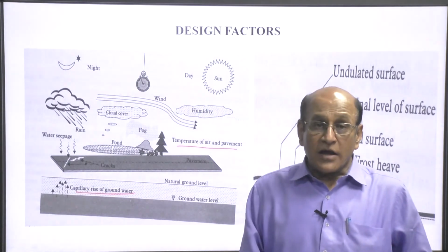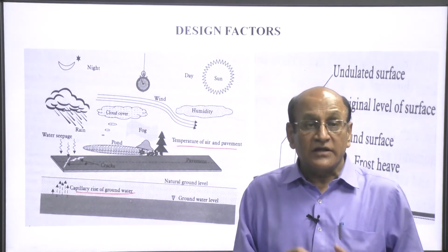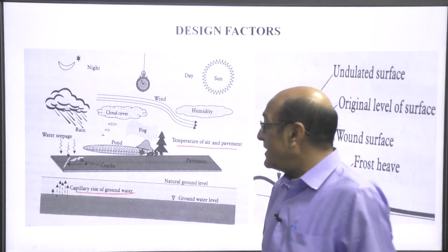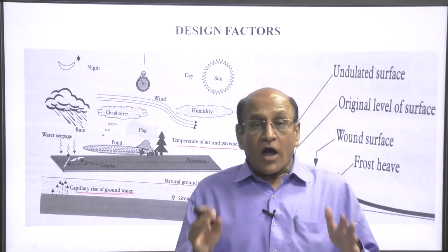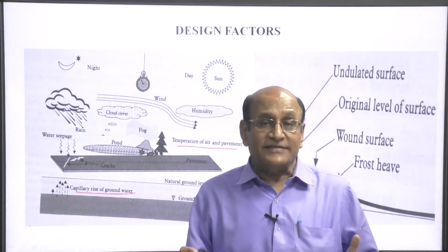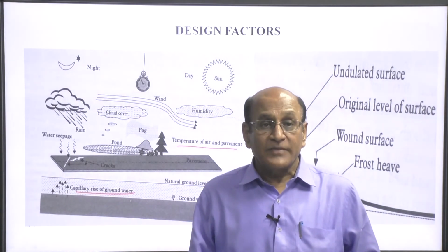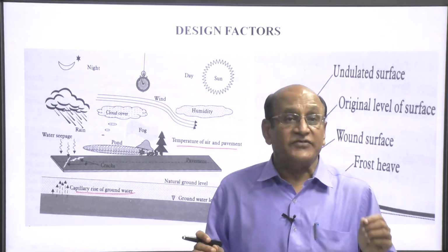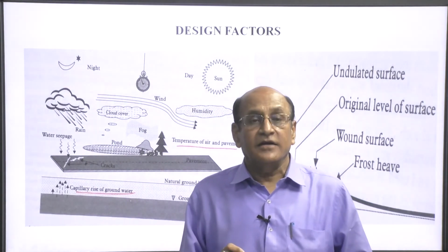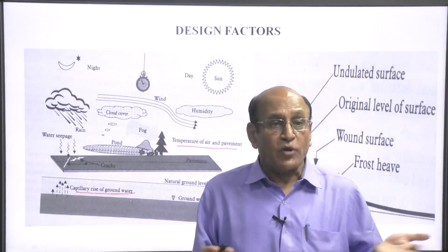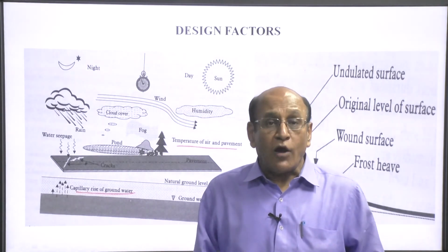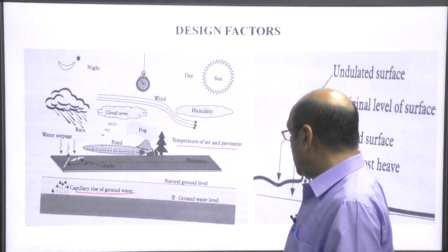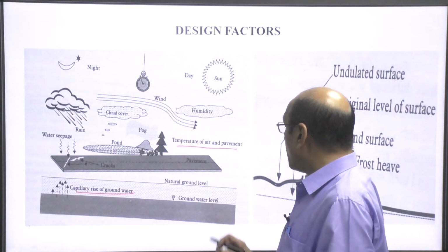If the capillary rise goes up, this will damage the entire pavement system. So, our subgrade material should provide a cutoff for the capillary action, meaning granular material should be placed into the subgrade, and this will provide proper drainage and will not allow water to go up. So, this will provide a capillary cutoff, and this is the natural groundwater.